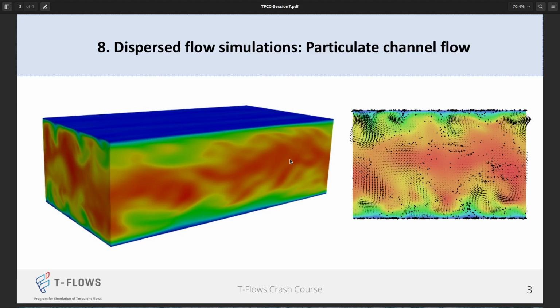Also, you should know how to tweak maybe the time step, or you can play around with the turbulence level, what's the input, what's the output, put different boundary conditions and see what works for you and what doesn't. You can increase the particle size, and you can maybe put an initial velocity for the particles instead of releasing them from rest. All of these options you can play around with to train yourself on how the code works. And as I said, we're just scratching the surface here about particulate flows, and you can always learn more and more.